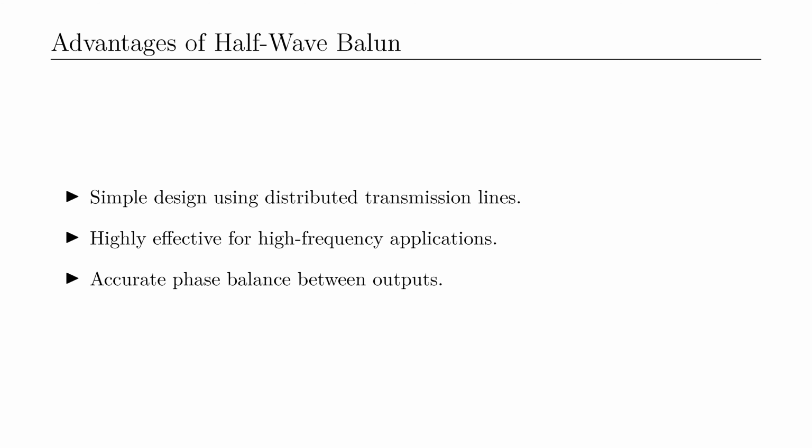The half-wave balun offers several advantages. Its simple design is based on distributed transmission lines. It is highly effective for high-frequency applications, where distributed components excel. It ensures accurate phase balance between the output signals, providing reliable performance in critical RF systems.